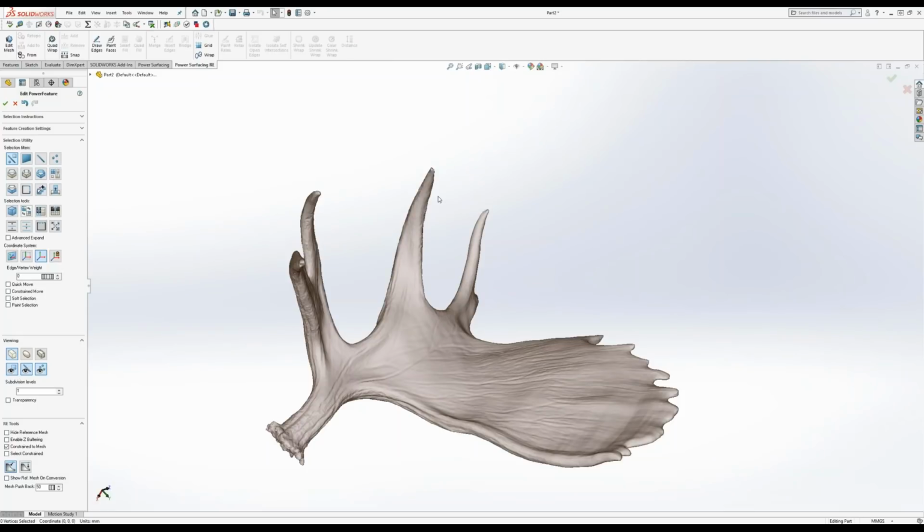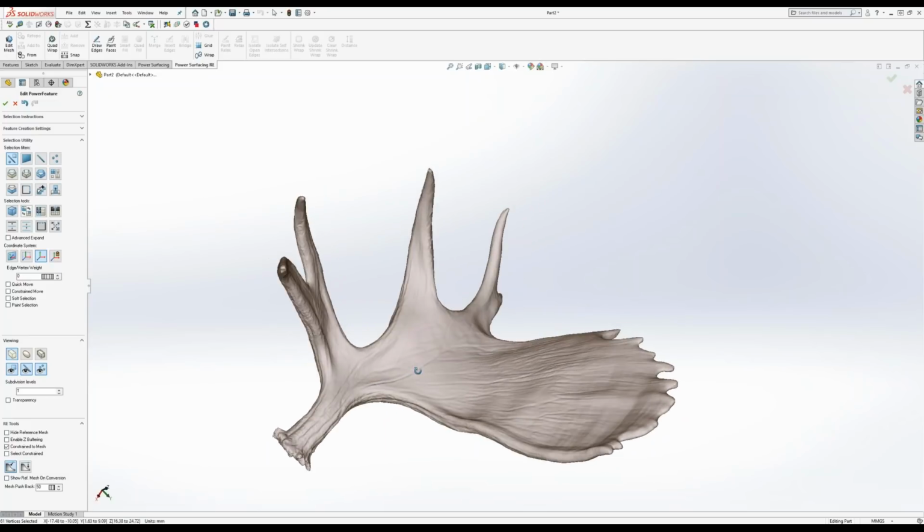Not much. I would say the main difference is that you're exporting to a step file, and you don't have your SolidWorks geometry right there with you. In other words, you can't easily create a cylinder and import it and use your SolidWorks tools on it. But for purely organic shapes, like for this guy, probably wouldn't be necessary.